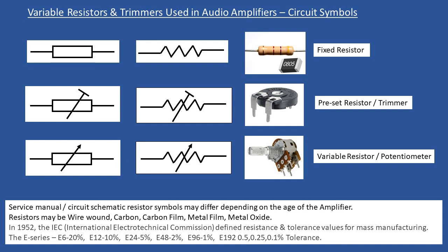potentiometer which is used for an audiophile type amplifier, and it would not be uncommon there to find these resistance values typically of 0.1%. You can of course get resistance values even more accurate than that, and then what we refer to is parts per million in terms of tolerance. So if anyone is interested to look at that in more detail, you can look up high precision resistors and it will come back in terms of parts per million.